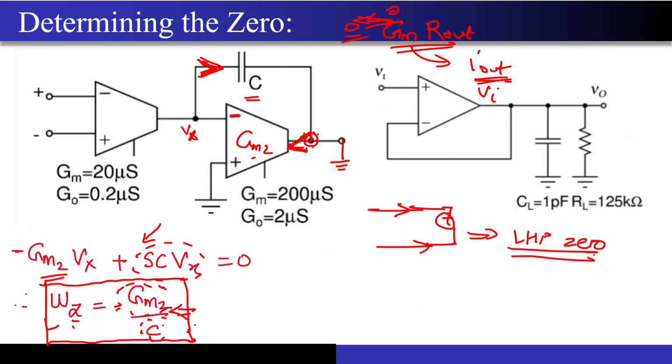Yeah, correct. Remember this Vx that you had applied over here, you applied at the negative terminal, correct? So the output is nothing but the Gm times whatever Vx you have applied. If I talk about the transconductor, the current would have been Gm2 times Vx if I had applied the Vx on the positive terminal. But since I am applying Vx over here, it will be minus Gm2 times Vx. Now if I have to remove this negative, then the direction of the current at the output has to be changed from right to left, correct?